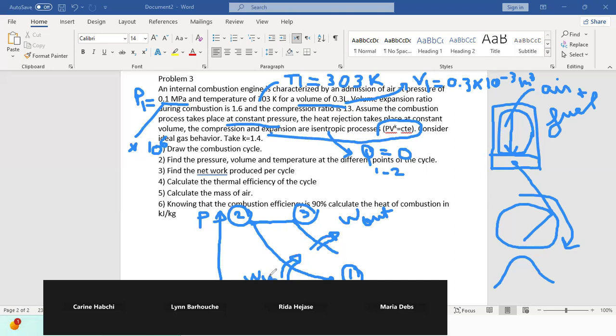And during the combustion process, we have input of heat. Since we have here a constant pressure process, during combustion, at the same time, we have input of heat, but we have also production of work because the expansion has started. So you have here W out 1. So the work will be delivered in 2 parts. First, from 2 to 3, then from 3 to 4.